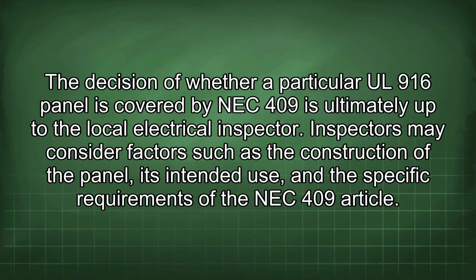The decision of whether a particular UL 916 panel is covered by NEC 409 is ultimately up to the local electrical inspector. Inspectors may consider factors such as the construction of the panel, its intended use, and the specific requirements of the NEC 409 article.